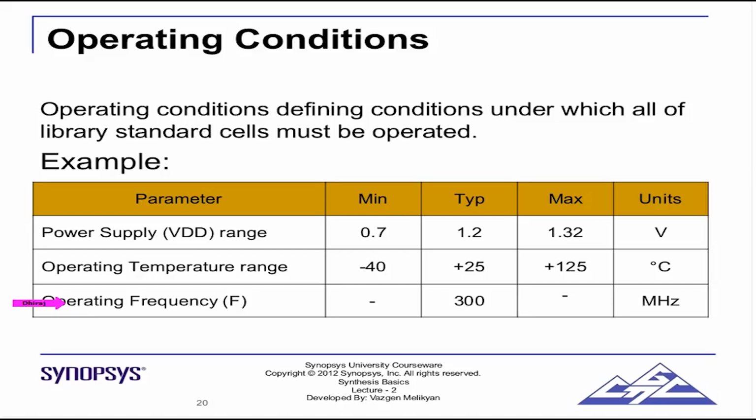That means we'll have libraries. For a standard cell library, let's choose the 1.2 volt technology, 90 nanometer for example, and let's say that a 90 nanometer design will work on 1.2 volt. You are designing a chip of 1.2 volt. Now we need to make sure that the chip works below 1.2 volts, because most of the cells in the design will not be getting 1.2 volts because of the IR drop.